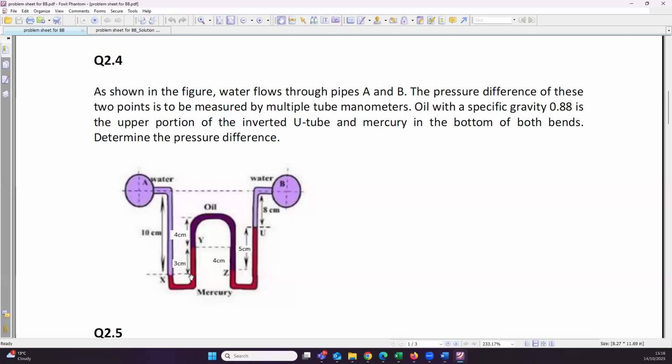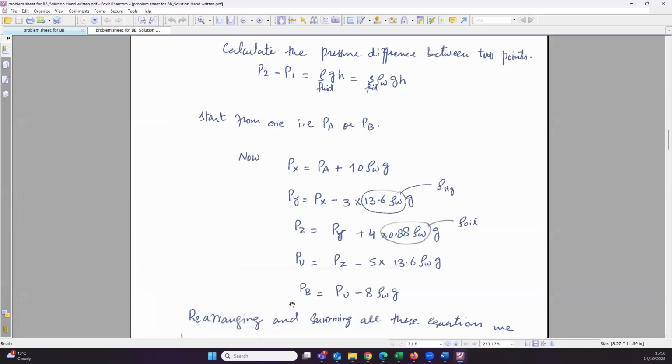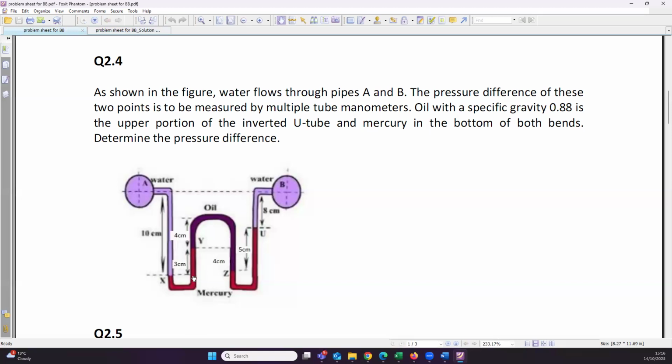So the pressure at X dash will be exactly the same as the pressure at point X. Okay. We also want to know the pressure at point Y, so you again have to use the same method of calculation. If you go back, the pressure at point Y will be PX, that is the pressure at this point. And then because you are going in the upwards direction, the pressure will become negative. Okay, when you look down, the pressure is positive because of the weight of the fluid.